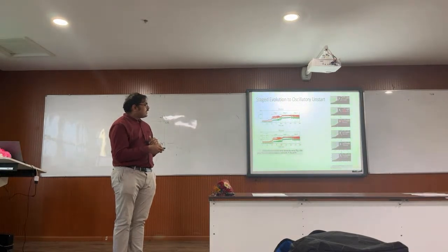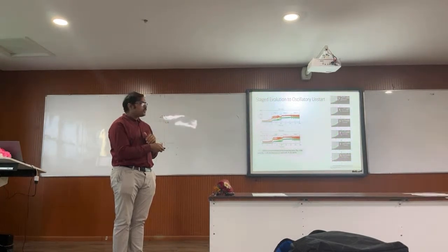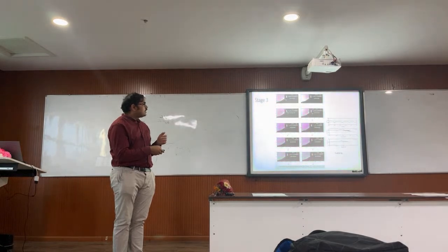We again see, like we saw in the previous case, that one shock comes out and detaches over here, you get a detached cowl shock here, and you get a supersonic jet. For quite a long time, this jet stays, the system stays there like that, slowly increasing its amplitude, and then finally it goes into full-blown unstart.